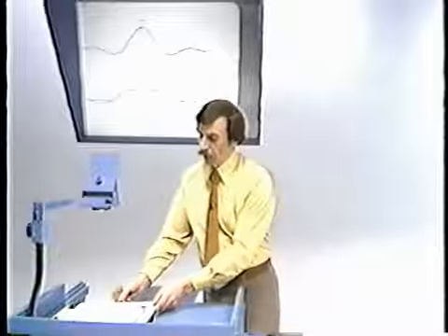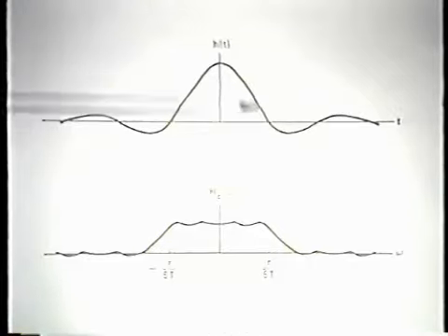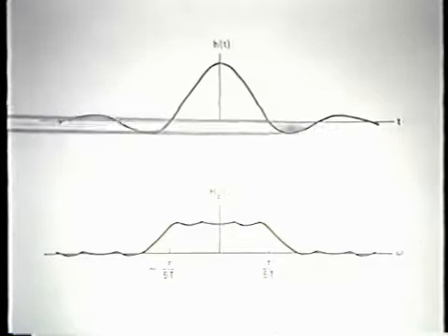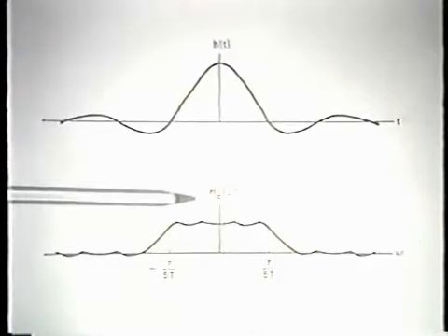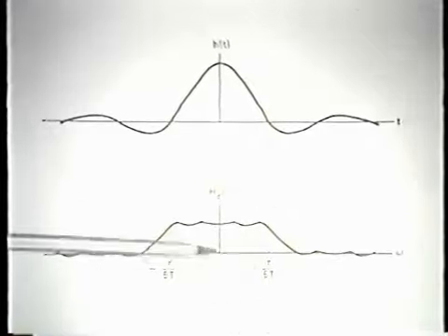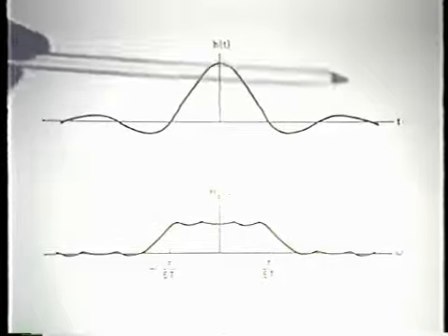So, in the frequency domain and in the time domain related to the continuous time signal, the associated impulse response is what I indicate here, a band-limited interpolation of the discrete time impulse response and time-scaled, in fact. And the frequency response, following the discussion that we've previously gone through, is a frequency-scaled version of the one associated with the digital filter. Well, the first thing that I'll want to look at is the impulse response.